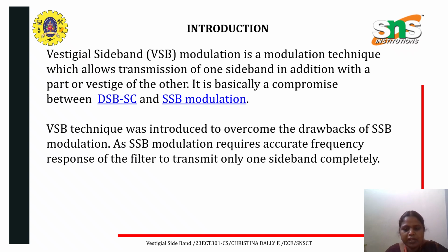We have so many techniques in amplitude modulation. We have the double sideband, the next one, double sideband suppressed carrier, single sideband, and the last one will be your vestigial sideband. We have discussed what amplitude modulation means and why the VSB technique was introduced, because some drawbacks are present in the single sideband. We have discussed the two sidebands, that is LSB and USB. SSB modulation requires an accurate frequency response.